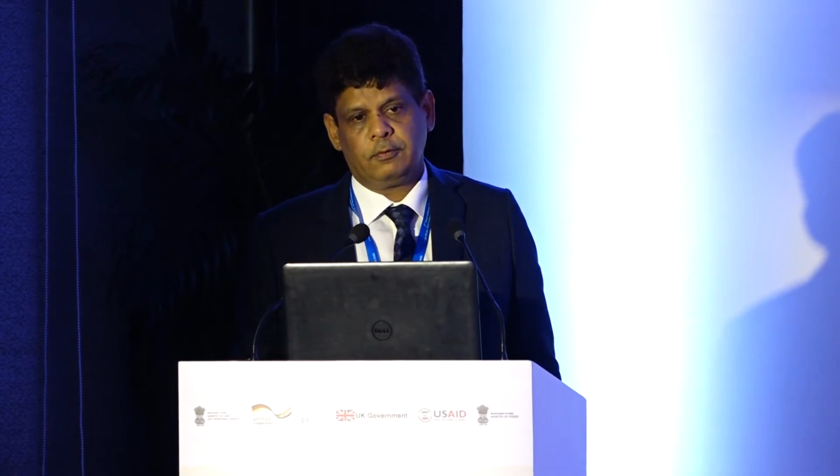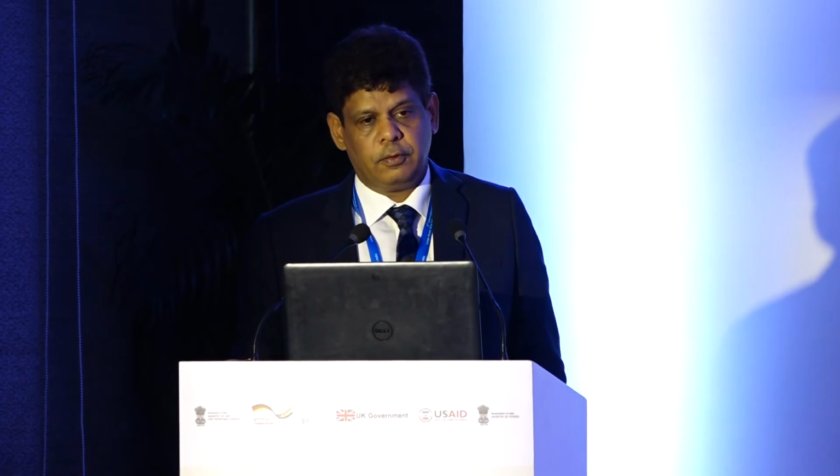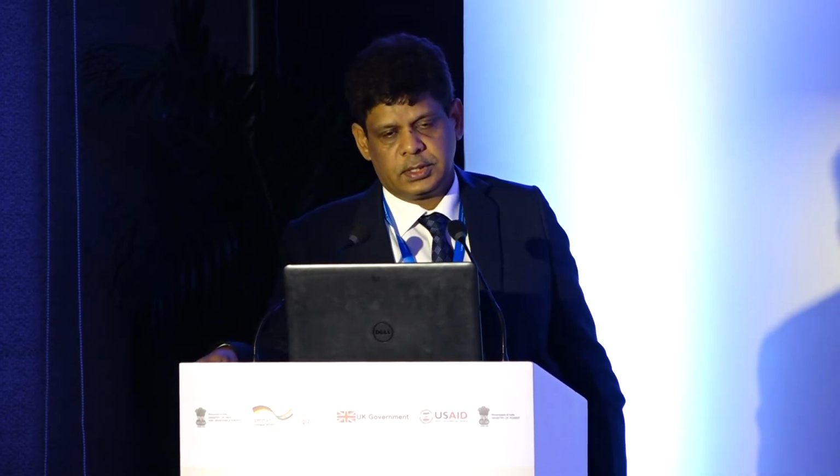What are the key steps involved? We'll show you the model which we're using and the key challenges which we are facing on a day-to-day basis. One more point I'd like to mention here is that for load, the forecasting is a day-ahead forecasting in blocks of 15 minutes, so 96 blocks in a day. And for RE, for wind and solar, there's a combination of day-ahead and intraday because as per the regulation, 8 revisions are allowed for solar and 16 for wind.